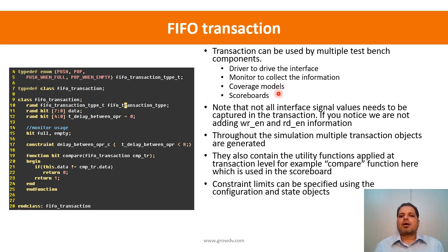And even your coverage models are going to use the same transaction to do the coverage collection, right? The monitors send whatever transactions they collect to both the scoreboard as well as the coverage models, and the same transaction type is utilized even for the coverage model.